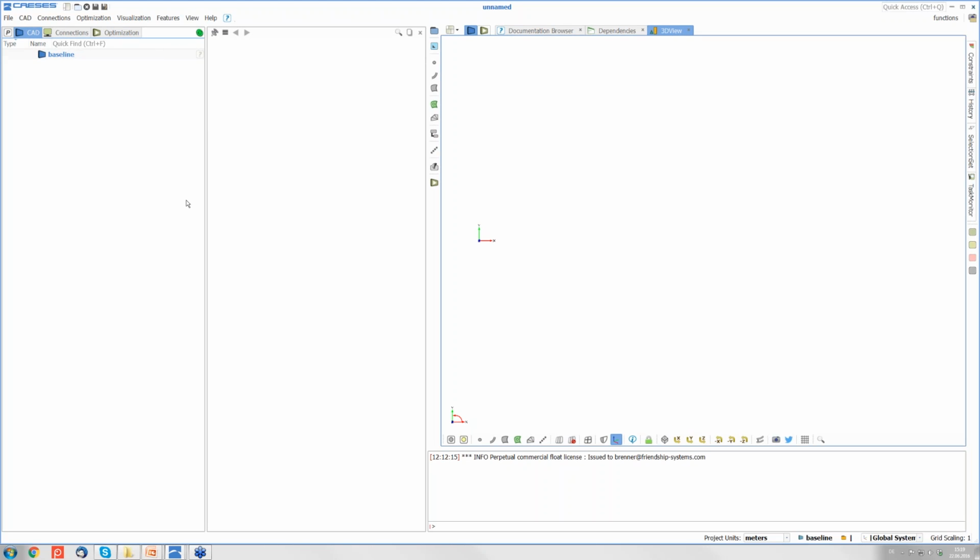And what we are using in CAESES to describe this parametrized cross-section through the surface is the so-called feature definition. The feature definition can basically be compared a little bit to a script. So you have certain input, in this case the parameters that describe the cross-section, and then you use this input to produce a certain geometry, and the geometry objects that you're creating within the script are the output of the feature. So let's see how this looks on a very simple example.